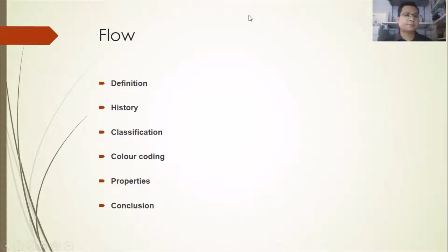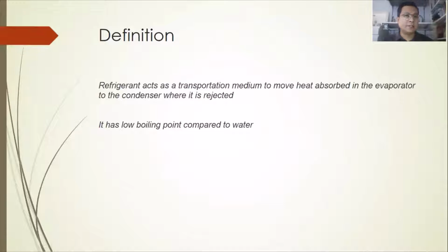Okay, we go first to the definition. Refrigerant acts as a transportation medium to move heat absorbed in the evaporator to the condenser, where it is rejected. So it has a low boiling point compared to water, because it is easy to transport the temperature, right?